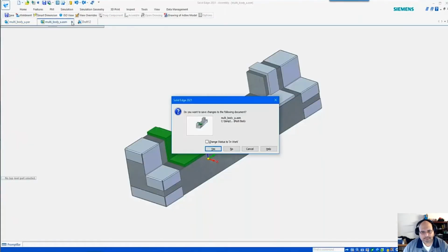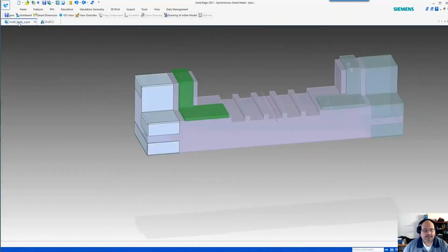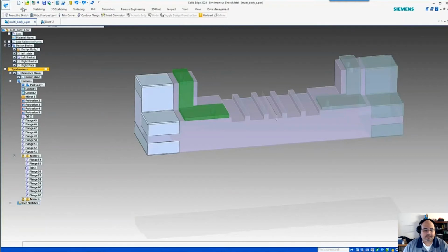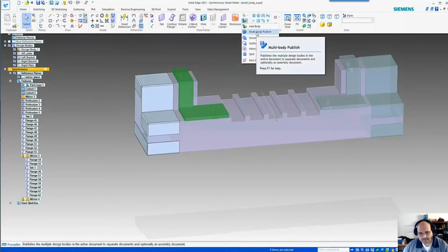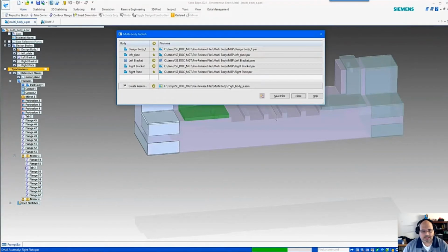let's go ahead and close this because you don't want to have it open when it tries to write a file. So kind of Windows 101 rules. Can't have a part open when you're trying to update. There we go. So there I got my clocks. And if I click save file over here, I can go ahead and update each one of those pieces of data, and Solid Edge will do its thing, re-update, reconnect the links and everything.